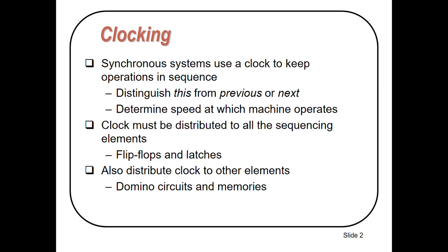A clock must be distributed to all the sequencing elements like flip-flops and latches, and also to other elements like memories and domino circuits. So the clock is an important part of sequential circuit design.